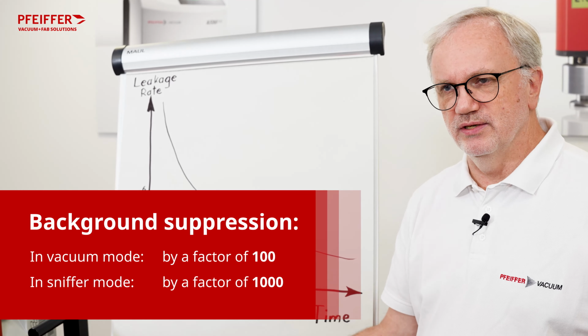But how does the zero function work? A zero function is a mathematical tool which reduces the background by a factor of 100 or 1000, depending on the model and depending on the mode that you are working in, so vacuum mode or sniffer mode.